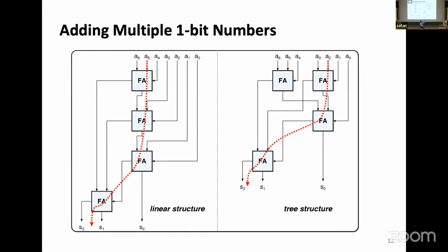And if all of these units are the same, which they are, right, full adders, and let's say the time it requires for this full adder to propagate from the input to the output is unit delay. In this case, I have 1 delay over this guy, the second delay, and then the third delay. The red arrow shows you how much time it takes. So this organization of the addition of multiple bits takes 3 steps. This one, 1, 2, 3, 4. 4 steps. So one of them is 33% faster than the other. Right? This one runs 4 gigahertz, this one runs 3 gigahertz. Okay?